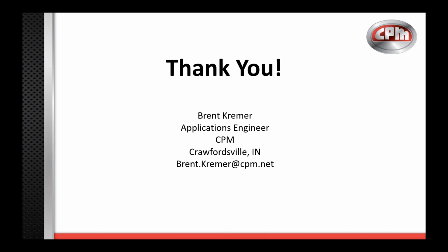Yes, this is Phil again. Thanks, Brent. That was very good. Touching a little bit more on maintenance, just before you get into the conditioner or anything in the pelleting line, please remember to lock out and tag your equipment just to be safe, and have safety as a protocol first, always. So with that, there are a few questions that were brought up that I will ask, and then Brent will answer them.